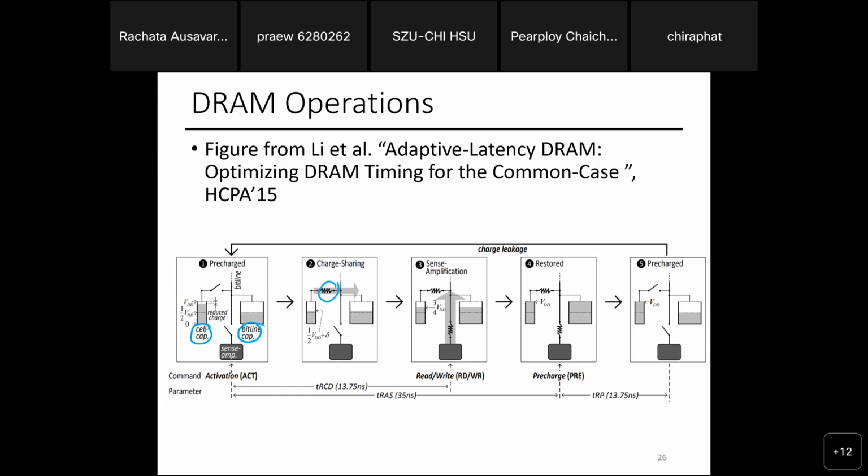Now my next question is, the bit line capacitor is exactly 1/2. If my cell capacitor is greater than 1/2, what's the voltage on both capacitors right now? If one of them is 1/2 and the other is more than 1/2, I add them together. Is it bigger than 1/2 or lower than 1/2? Bigger than 1/2. All right. So let's say the cell capacitor stores the value 1. When I close the switch, I get greater than 1/2.